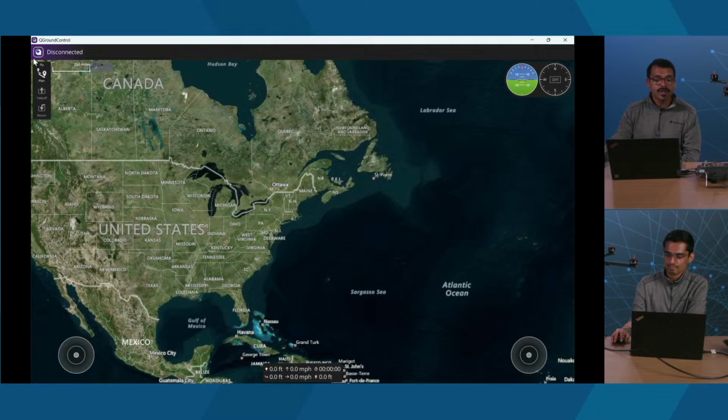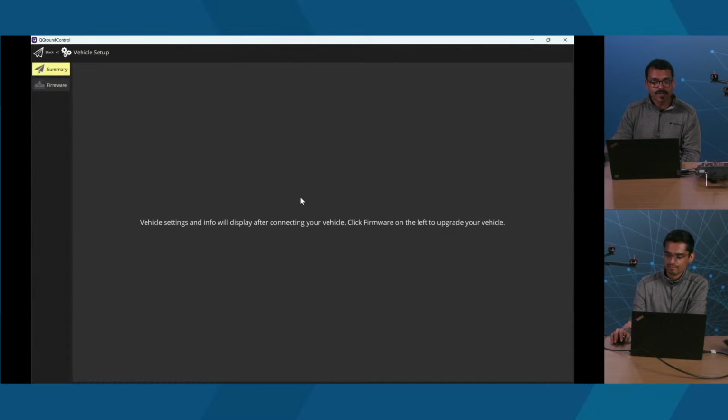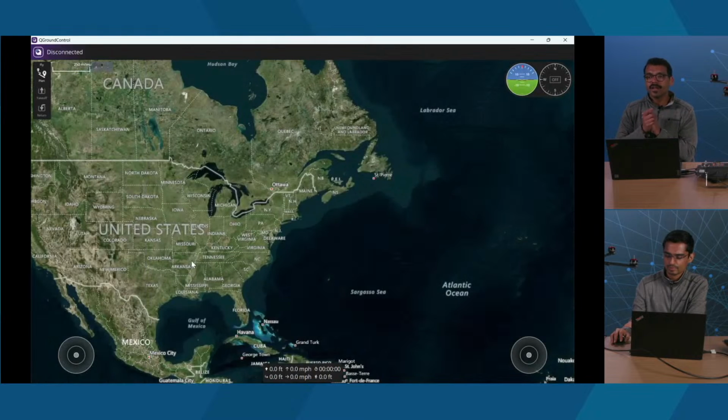But once it does, you are able to go into your vehicle setup and specify the airframe, and specify different things like where your motors are. What is motor 1, 2, 3, 4? What PWMs do you want to send to them? We actually have ways of increasing that. So in QGC now you'll see maybe there are 8 motors, 8 servos. If you're on 1.14, we have a way of making that go up to 22 or 30 different servos, 30 different motors. But yes, you do have to specify what airframe, what RC you are connecting with, and what kind of battery levels, whether it's a 4S or 6S.